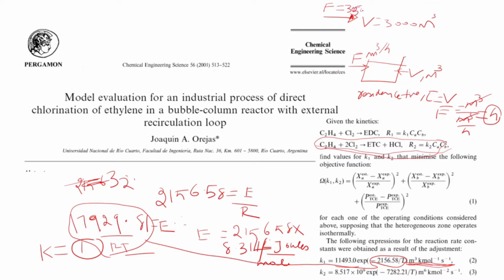We get 350 kilomole per hour, and then some additional amount, 364, or I don't remember exactly, kilomole per hour of chlorine. So it will be the total flow rate. The flow rate is fixed, and we need the residence time to be equal to 2.5814 hours.